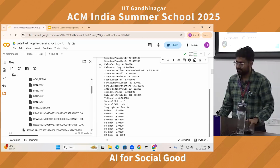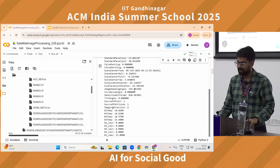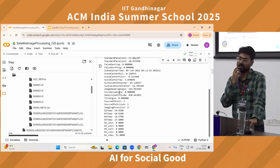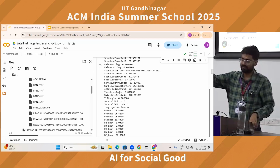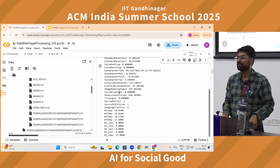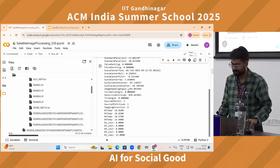Now, at the time of capturing the scene by the satellite, at what position the sun was, this kind of information is given here. So it is very important. Sometimes you want to remove the shadow from the image that you have captured, the cloud shadow. You want to identify that. So you know the sun is there, satellite is here, and the position of the cloud. Based on trigonometry, you can identify at what area the shadow is coming, and you want to remove that one. So in those kinds of applications, you can use this information.